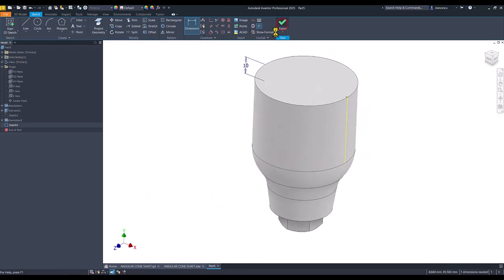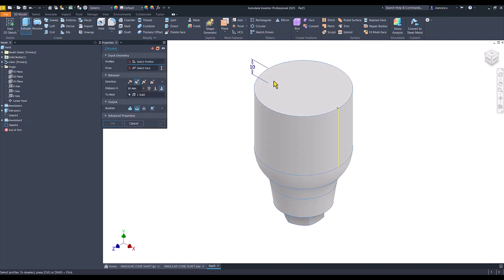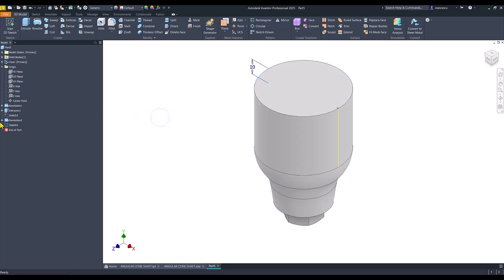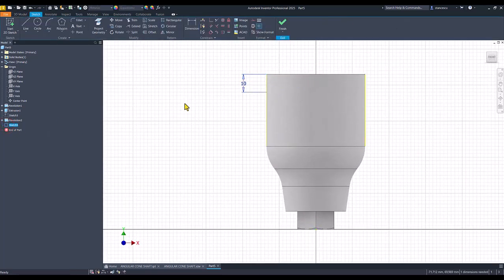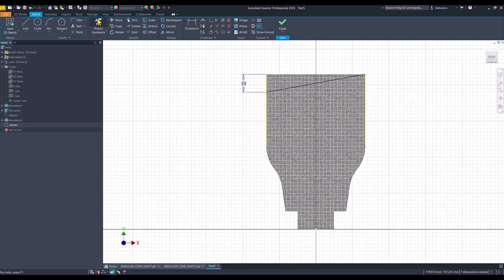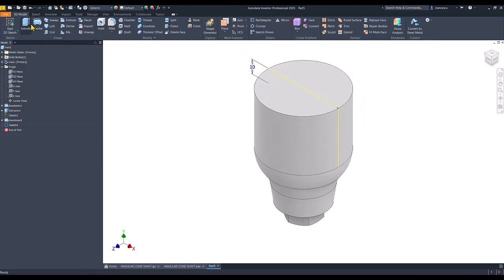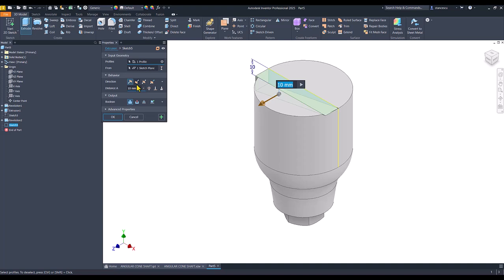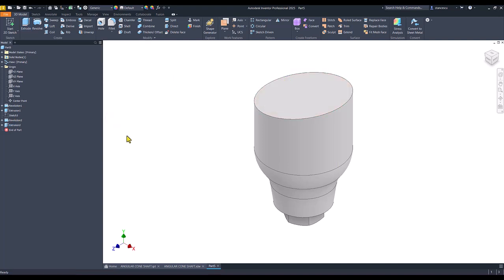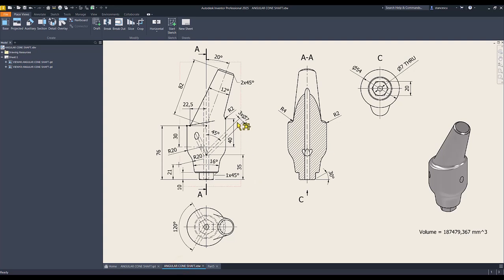Finish sketch. Extrude, triangle, select profile. I didn't draw this line. Mea culpa, my friends. F7, project this end line, and now we have the triangle. Extrude, symmetrical, with cut, all the way. Now the cone.